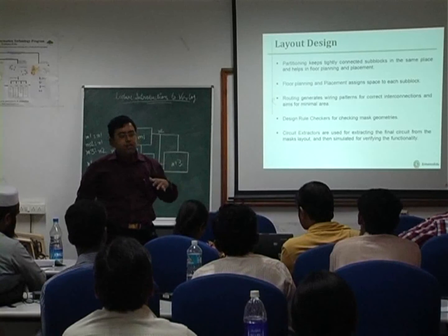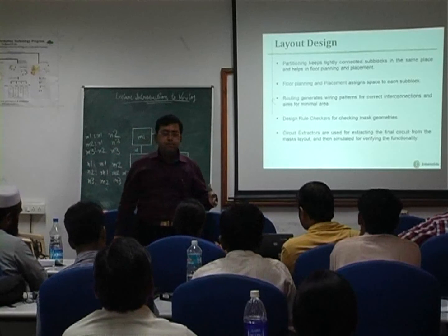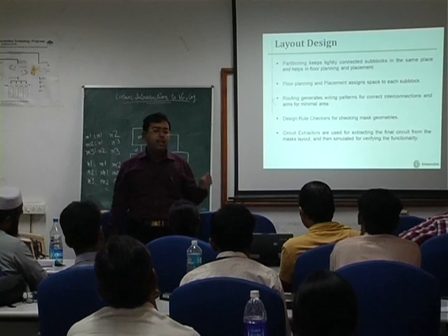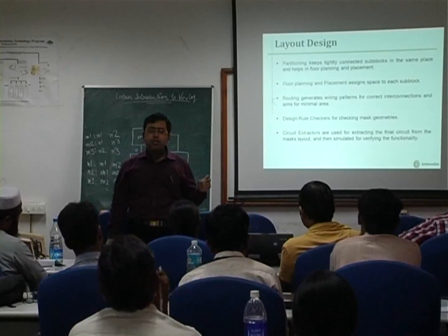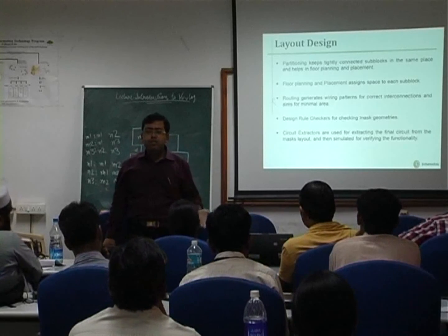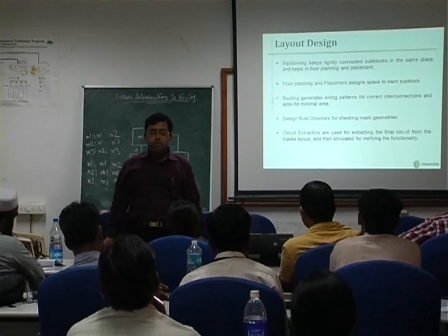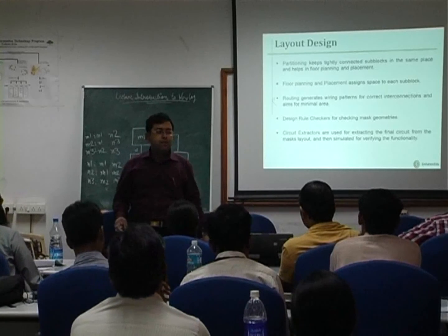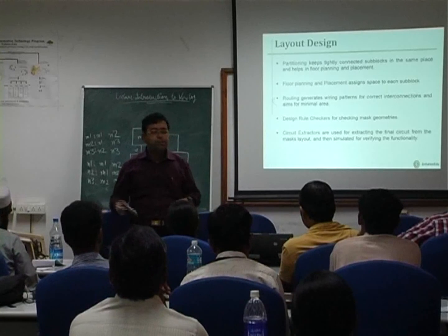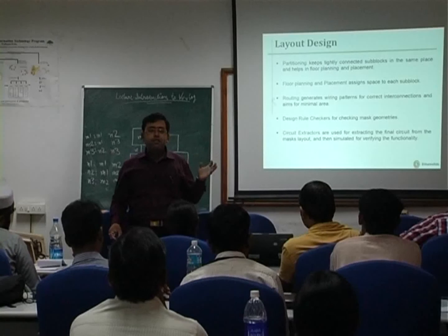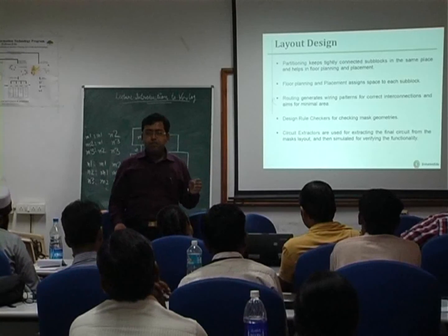And further down, when you come to the transistor level, you have to write equations and analyze the behavior of the circuit. So you have to use the IV equations for the different devices with which your circuit is made up of, and then analyze the behavior of the circuits, find out the node voltages, branch currents, and so on. So that is what we really mean by analyzing the physics of behavior of the circuit.